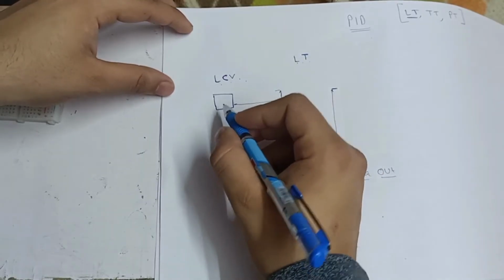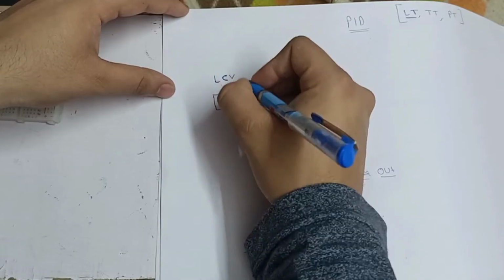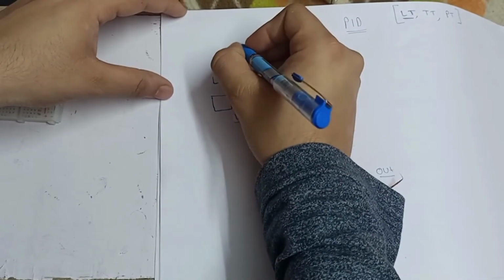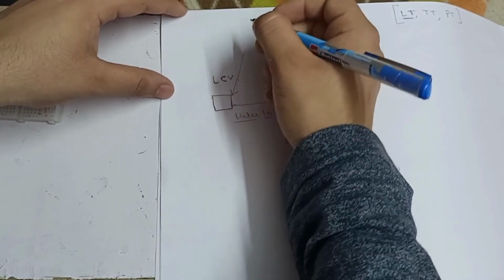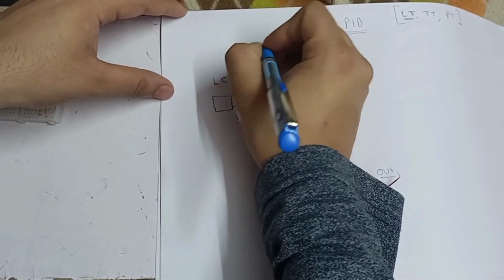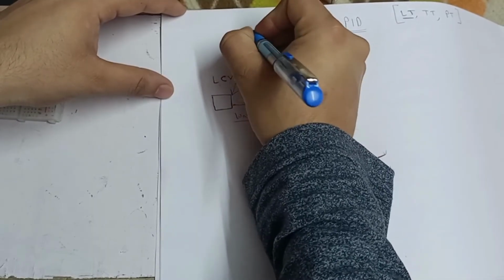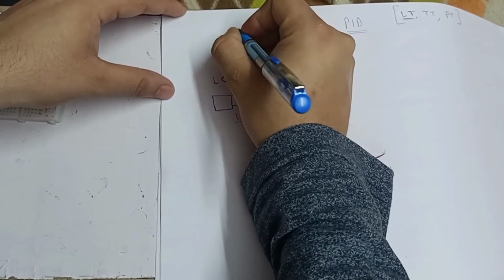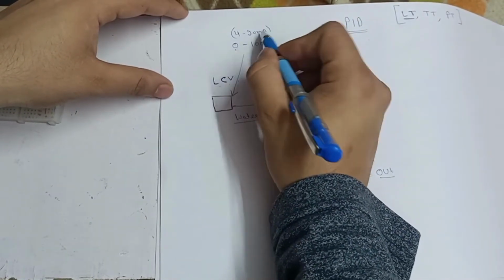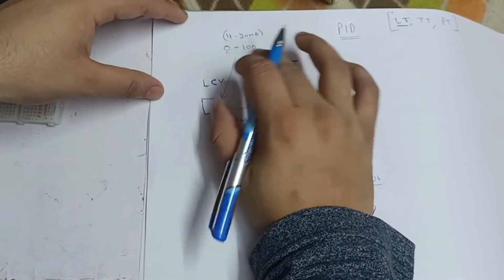It's very important because it's like an analog. Now I enter a comment here: this is like a liquid vary. We can see the variation 0 to 100. As per the comment you can change the value. It operates on 4 to 20 milliampere, which we convert into 0 to 100, meaning minimum is 0 and maximum is 100. We can choose this parameter.